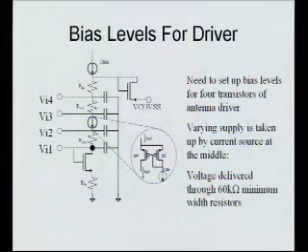Okay, now one of the things just to briefly touch on is how I set up the bias levels of this thing. Basically, I want everything referenced to the lower, essentially the VSS of the VCO. But I actually want to bias it above that. So I have a little bit of current into a diode, which sets up a higher one, and then I just have a resistive ladder. And the only trick here was to put in what amounts to a little current mirror right in the middle of the stack, so that when my supply voltage changed, I'd take it up on this place rather than across either of the individual amplifiers.